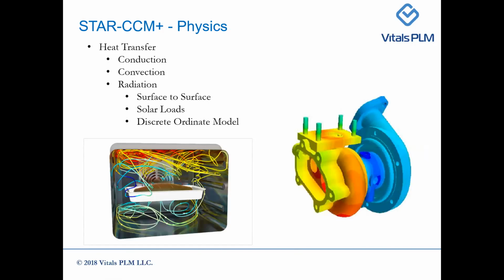STAR-CCM+ can simulate all modes of heat transfer in both fluids and solid materials, conduction, convection, radiation. In radiation, we have a surface-to-surface model, solar loads, and discrete ordinates model if the fluid absorbs heat.